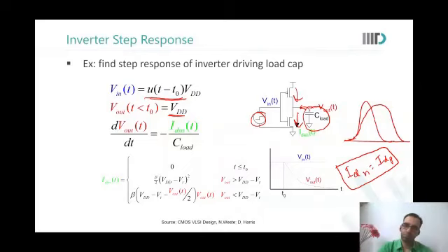Sometimes this PMOS will be linear and NMOS will be saturation, and this current is also going. Sometimes the PMOS could be driving more current to the C load. And let us look at it very simply. If we know the output is going to be 0 now, we know that this capacitance has to discharge. There will be a capacitor current, sir, actually. The charge that this capacitor has has to be sunk to 0.